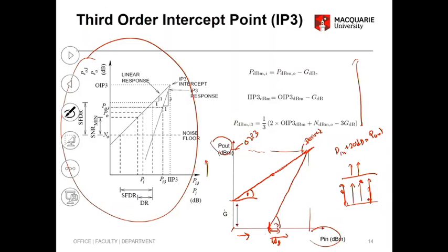Okay, so in your spec, I think it was 36 or something. Oh, what was it? I can't remember. In the assessment. Maybe it's 16 or something. Yeah, okay. So that means at 16 dBm output, your IMD levels and your output level are equal power levels. Now, if you look at the input power level where you have the IMDs and the output same, we call that your IIP3, input IP3.